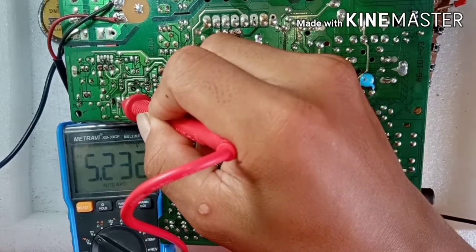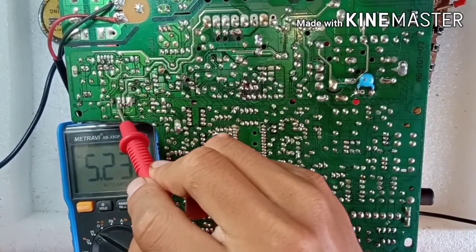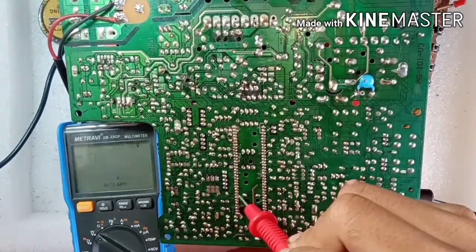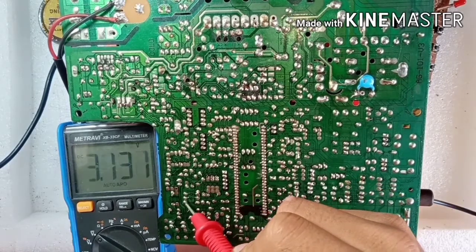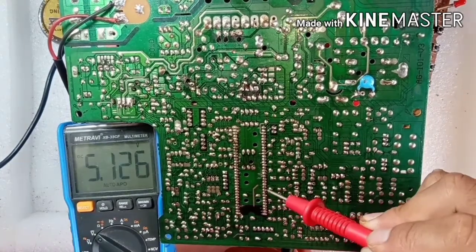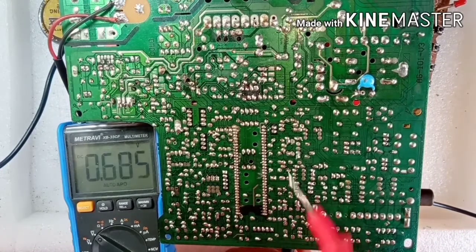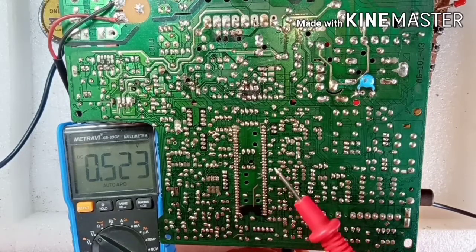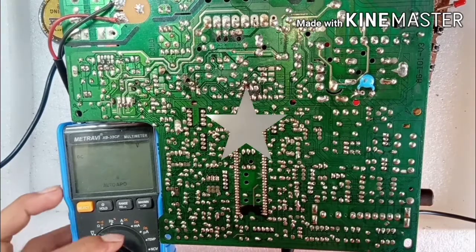So let's check if this 5 volts really gets to the main IC here. Let's follow the path here. Okay, we have 5 volts there, and there's a branch here again, so let's follow again. Alright, we have the 5 volts available to the main IC. These 5 volts are necessary for the main IC processor to turn the vertical IC on. I think the TV, if it works, must be working now.